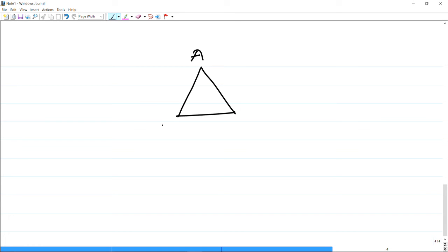Let us say these are the 3 sensors A, B and C, which are placed in these 3 locations. So, like that you should place them in a particular pattern or in a particular shape, so that you know how exactly they are placed, and as I said, what is the distance between them, so that we can identify the locations of the acoustic emission source around them.